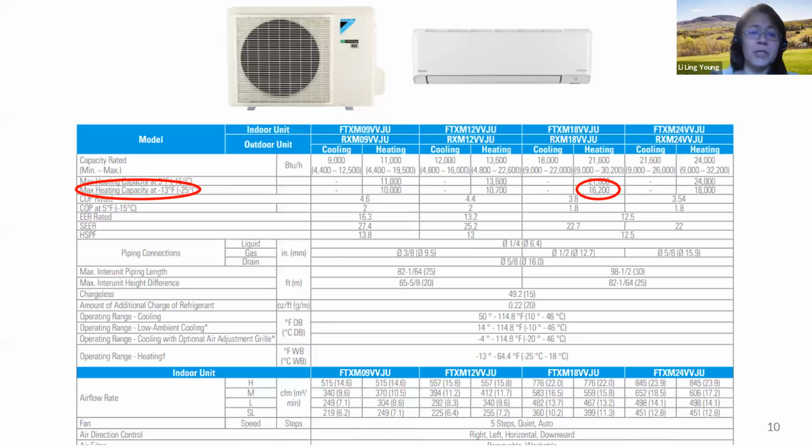But in any case, you can see there on the left, it's saying max heating capacity at -13 degrees. I do not care what the rated heating capacity is at -13 degrees, because at -13 degrees I want everything that heat pump can give me. So the max heating capacity at -13 degrees, under that particular model, is 16,000 BTUs an hour. This is the information that would go into that other screen with the lower checkbox. You add this information in, it extends the capacity line out to the left. And that's a pretty good heat pump because you're not losing that much.